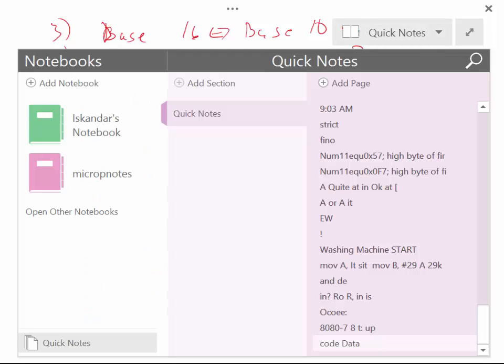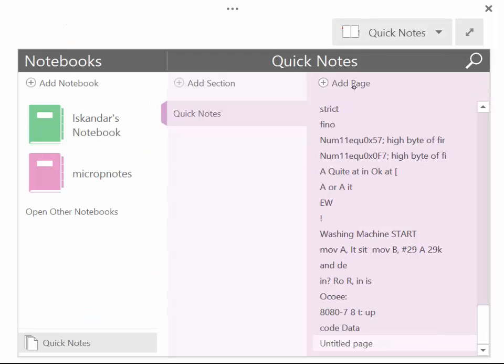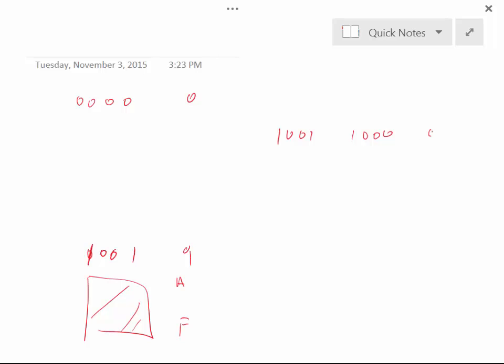Binary coded decimal, right there, is 0000 all the way to 1001. This goes 0 to 9. We don't use A through F. Those are not used. And to convert from binary coded decimal to decimal and back is just the same as doing hex. So if you see the number 1001 0000 0011, that is simply 903 in base 10.